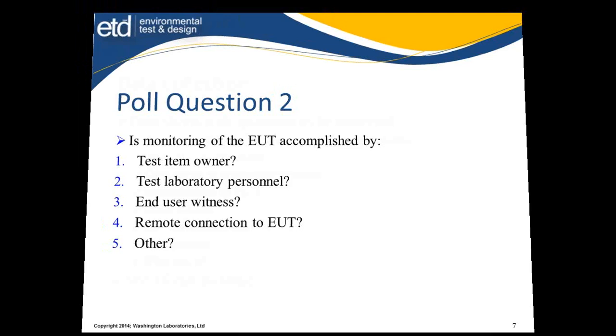Data collection. We all need to have data sheets. These data sheets need to be kind of thorough with the questions to be answered. We shouldn't have a blank page for us to write in data. It should be the questions as to what needs to be supplied. For instance, where did the accelerometer, control accelerometer, get positioned for vibe? Where did we place the sensor to know that the impact was there? What did we do for thermal monitoring to determine whether the unit was stable or not?